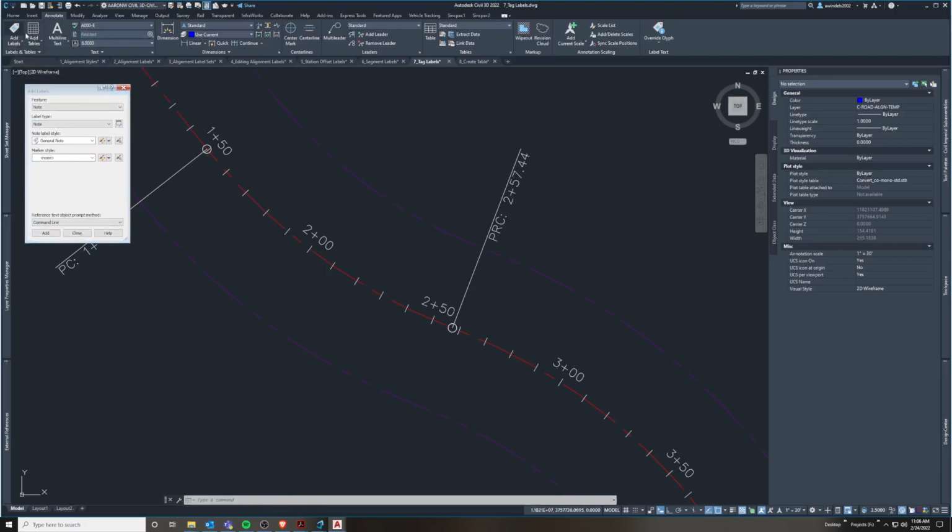If you're going to learn anything in Civil 3D to label, learn this, how to get to here, and this will take you most of the rest of the way. You just have to go to the right entity, alignment. In this case, we're going to do some different stuff here. We're going to say multiple segment, so it will label multiple things at once, as we learned in the last section. We're going to go to circle tag for both. Make sure it's on. That circle tag is for line label style, and circle tag is also on for curve label style.